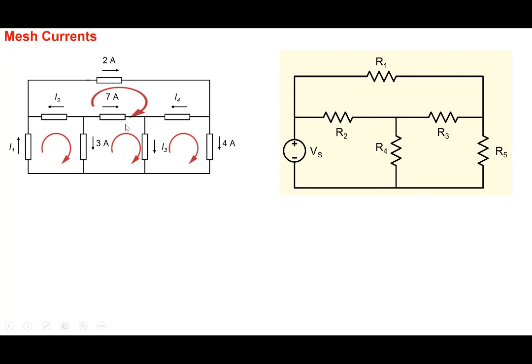Well, let's look at this particular circuit. In this case, we have this mesh, this mesh, and this mesh here. The first step in mesh analysis is to identify all these meshes and associate a current with each one of them. Let's say current I1 flows through this mesh, current I2 flows through this mesh, and current I3 flows through this mesh. Note that these are temporary. The actual current flowing through R2 is neither I2 nor I1, right?